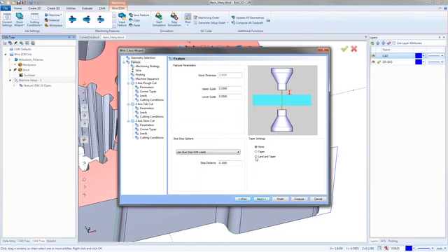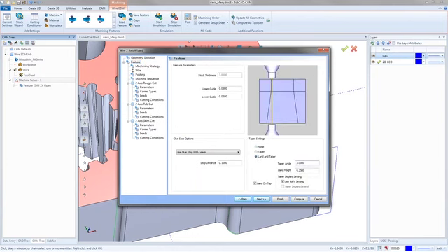Now, I don't know what the full land and taper is. I think the land height, I'm just going to guess and say it's 1/8 of an inch. Taper angle, we'll say 3 degrees. I didn't really mess with this too much. But one thing you could do is program this as a 4th axis if you wanted to.